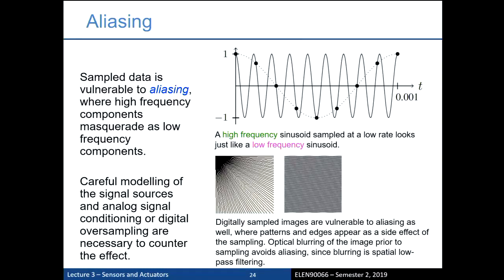So it's a high-frequency sinusoid. It's 9 kilohertz, that sinusoid, and it's sampled at 8 kilohertz. Okay, so immediately you should have some warning bells. If you've done any signal processing, Nyquist sampling theorem, all that sort of stuff should be going off in your head. 9 kilohertz, we're sampling at 8, and the samples, those big black dots there, if you reconstruct it, it looks like a 1 kilohertz signal.